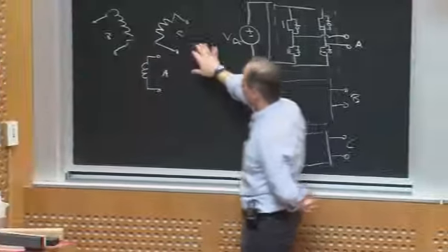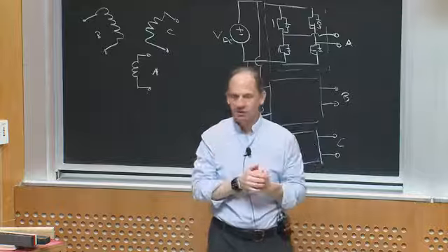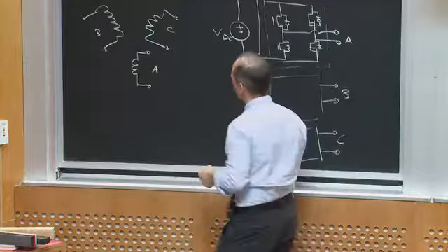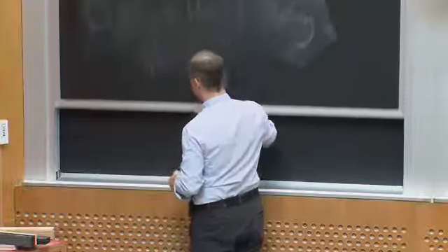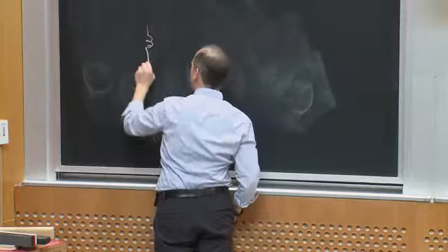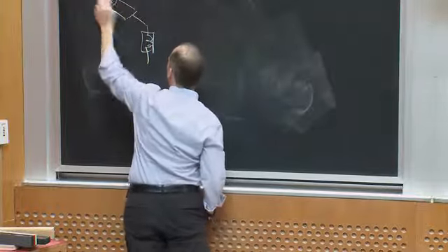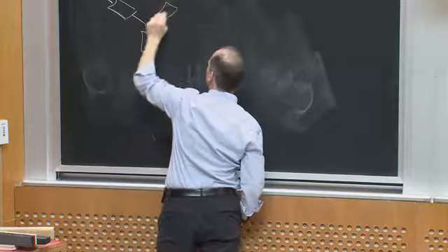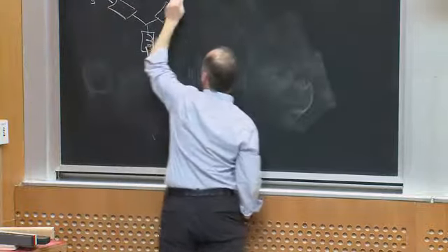However, the vast majority of, say, three-phase motors are not just separate windings connected like that, right? Typically, if, for example, I have a three-phase motor, what I will have is either something connected in Y, right, where this is one motor winding, a second motor winding, and a third motor winding, right, where I'll have A, B, and C, okay?